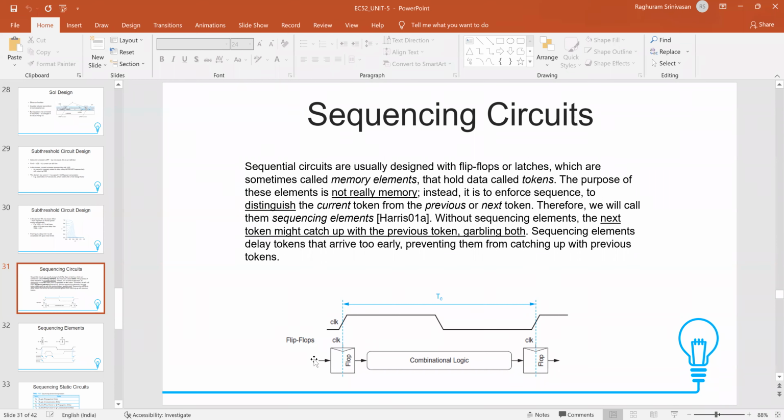We should take the correct outputs. And the output side flip-flop is doing something similar, but for our particular combinational block. We should not give out partial outputs. You might have 4 outputs, some combinational block might produce 5 outputs, etc. Only when all the outputs are ready should they be passed on to the next block. So that is what these two flip-flops are doing. They're basically controlling the sequence of the inputs and outputs being produced so that the correct inputs are sampled and the correct outputs are sent to the next block.